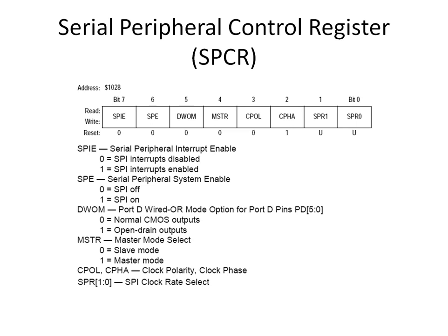And so therefore, my intention here is to be in control of the serial clock line, to control the timing of the clock line with the data being placed out there and being sent out, so that the receiving end would be able to receive it properly. And since I want the 68C11 to be in control of that, I'm going to set it as a master. So the master would be set to a 1.